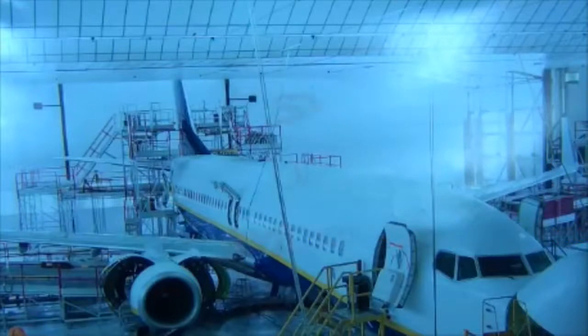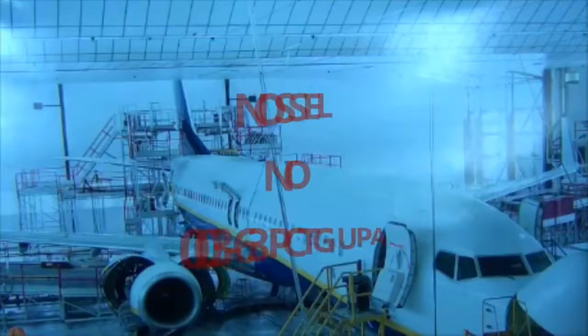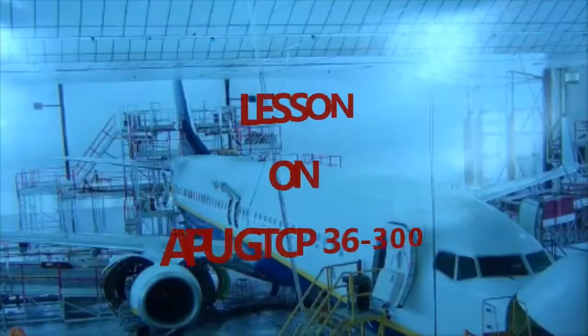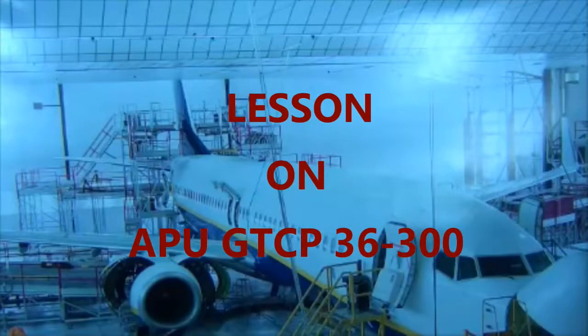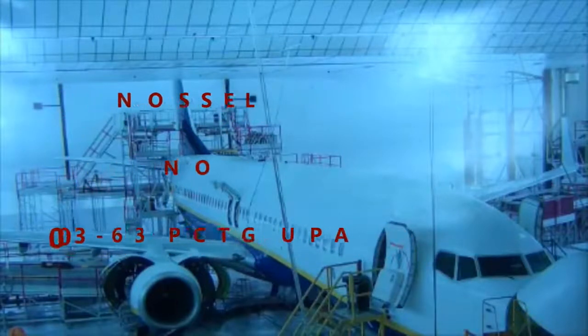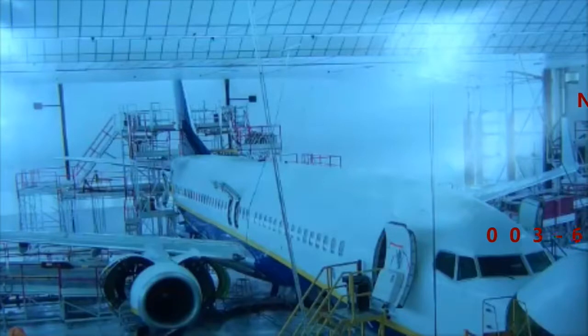And with the diverter, it's making sure that fluids, you could have all kinds of stuff. You've got oil, obviously, hydraulic fluid, de-icing fluid in those lines, fuel, water, things like that you don't want to get into the APU during flight or otherwise. While it's running, in operation, there's a potential for some of that fluid to get into the APU. You don't want that, and that's what the diverter is there to prevent, all that from entering the air inlet so it doesn't go into the APU. So that kind of gives you an idea.